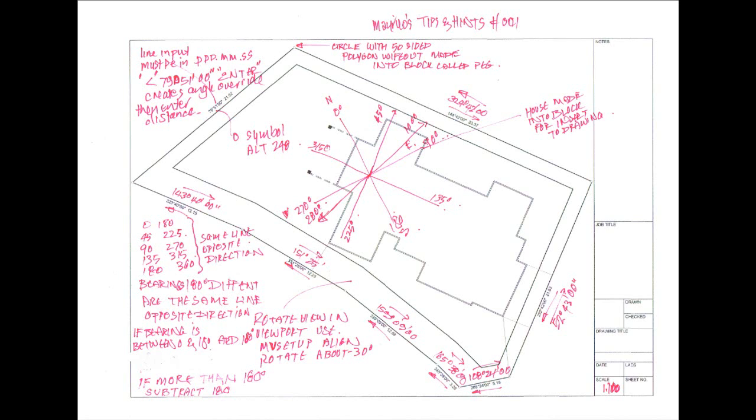I drew my house in millimeters, and I wanted to import it into this drawing, so I actually had to scale it down by 1000. I just went scale and 0.001 and scaled it down so that it was in the same terms as the drawing here. Then you can create it as a block and move it into the lot, and then you've got to try and position it how you want it. As a block, you can move it, rotate it and scale it. They're the three things that you can do.